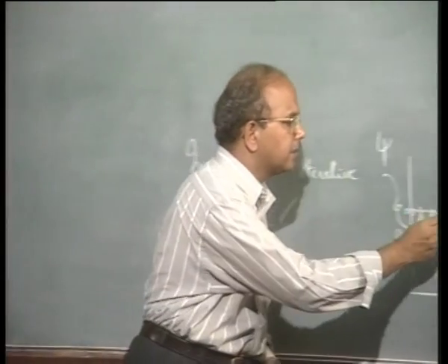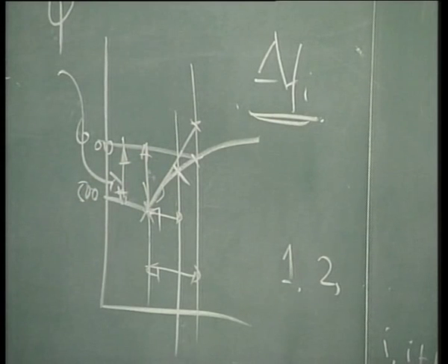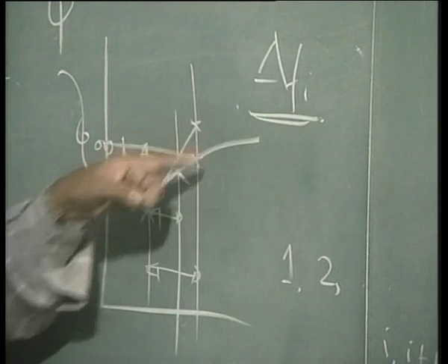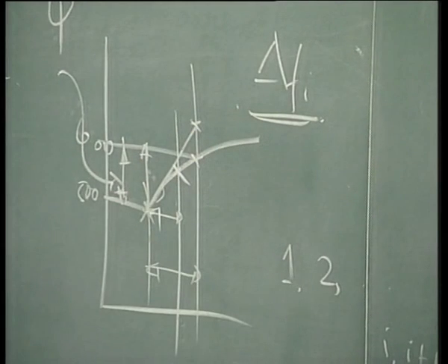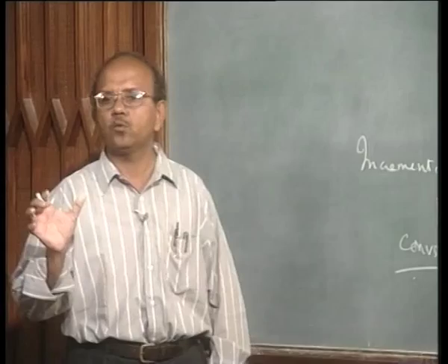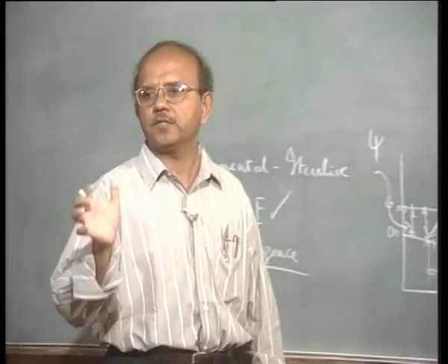I am still here. Why? Because I have essentially linearized, this is called linearization. I have essentially linearized a nonlinear curve. This is exactly what would result in a Newton-Raphson form. Psi plus dou psi by dou d into delta d is equal to 0 is what would give you a Newton-Raphson scheme.